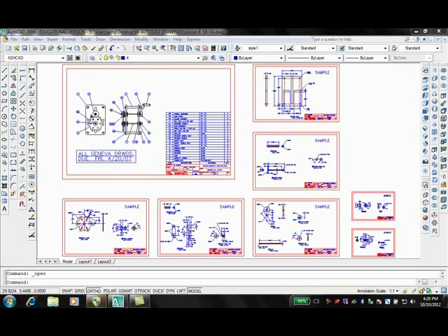Remember that DIMSCALE sets the overall scale factor applied to dimensioning variables that specify sizes, distances, or offsets, and LTSCALE is used to change the scale factor of line types for all objects in a drawing.